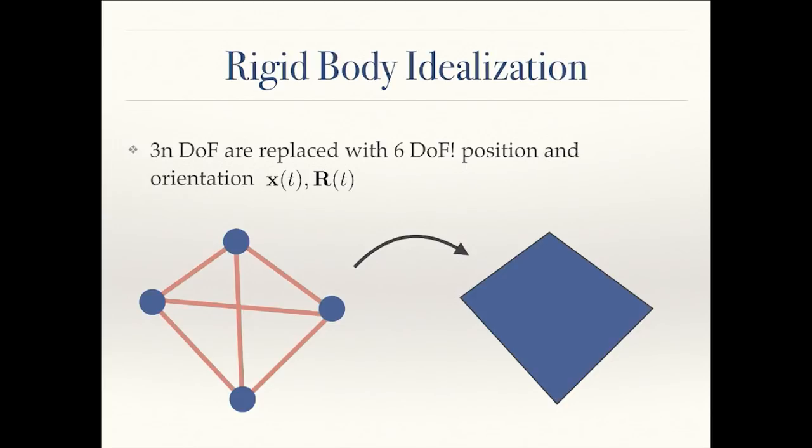If I point it to different points on the sphere, how many numbers is that? Well, a sphere is 2 because we have latitude and longitude. So that's 2 more degrees of freedom for where it's pointing on the sphere. And then the third one comes from the rotation about its own axis. That's just one way to parameterize orientation, and there are infinitely many ways. Now, I wrote R here for rotation matrix. In practice, it's very common to use what are called quaternions to represent orientations and rotations in physics-based animation, but we won't talk more about those today.